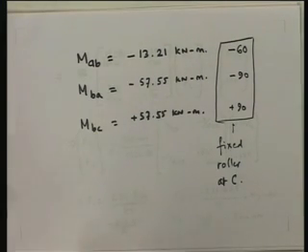What has happened to the member end moments? They've gone down. Why? When I made the fixed roller into a hinge roller, what did I do? I increased the flexibility of the structure. Now, here are the points I have tried to make. When you make a statically indeterminate structure more flexible, A, you increase the displacements. We've already seen that the displacements are significantly larger than in the fixed roller case. And B, you make the member end moments smaller. Why?